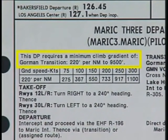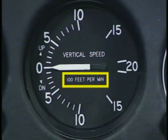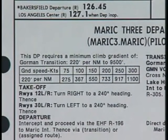If you filed and expect to be assigned the Gorman transition, the minimum climb gradient is 220 feet per nautical mile to 9,500 feet. Note that the climb gradient is in feet per nautical mile. Since your VSI only measures feet per minute, you must convert the climb gradient into something which is easily measured. Jeppesen provides this information in a convenient table for various ground speeds. For example, if your ground speed is 100 knots, you must maintain a climb rate of at least 367 feet per minute.